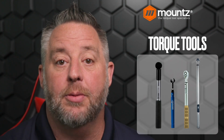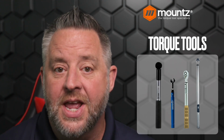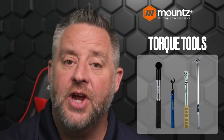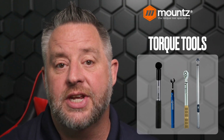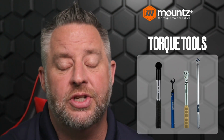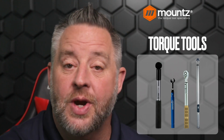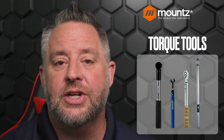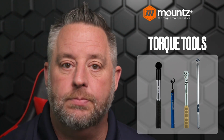And that can be very problematic, again, where you may have a critical type of torque that you need to achieve. So if the operator is very slow and deliberate and waiting for that, these wrenches can be very accurate, but again, they are very operator dependent on who might be using that, their mood or their size and strength. So again, the click wrench is a very operator dependent type of tool.